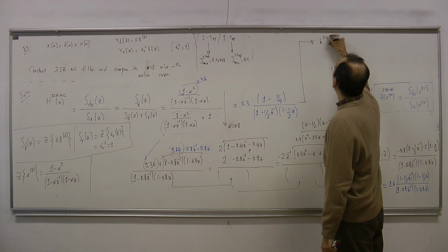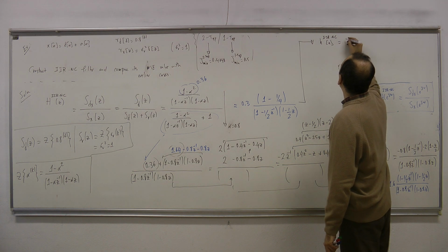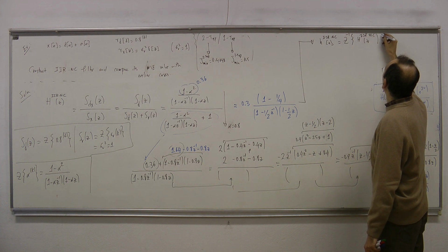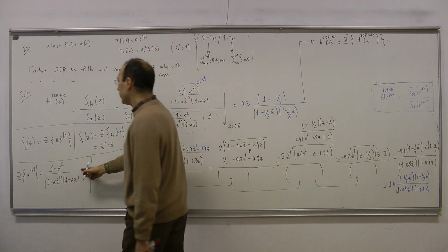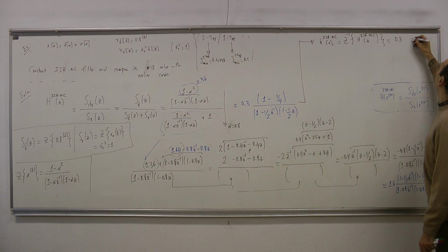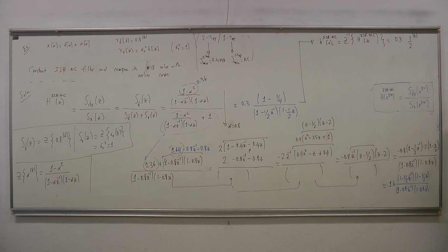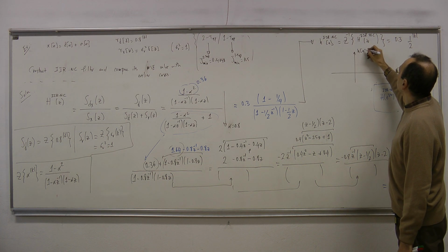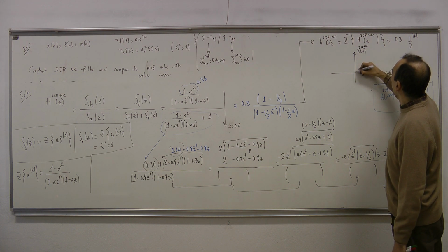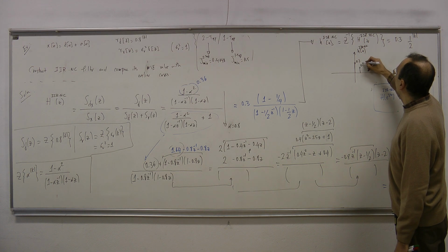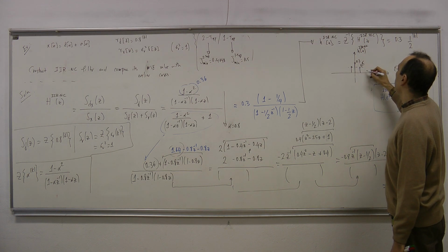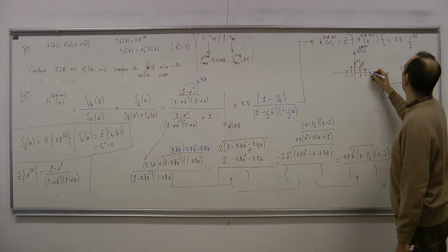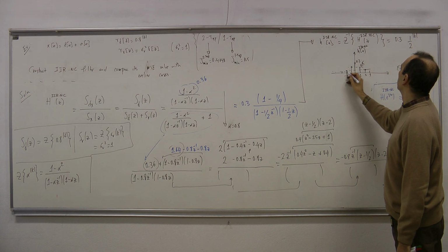Then h IIR non-causal of n is the inverse Z transform of H IIR non-causal of z. Now I want to use this, so I get 0.3 times 1 over 2 to the absolute k. So if I sketch this impulse response, it's like 0.3 over here, 0.15. So indeed it's an even sequence, so am I right? So 1, minus 1, 2, minus 2. This is 3, minus 3.